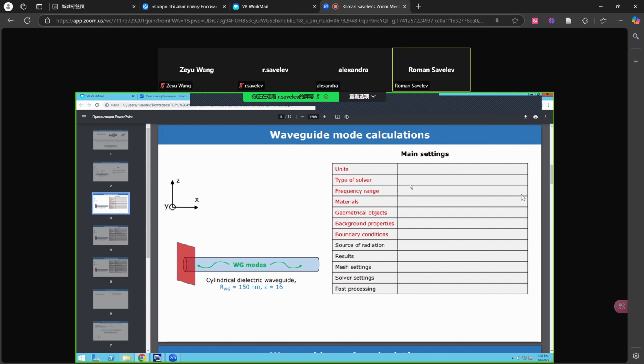So let's start making the model. Let's consider the first half of the settings that we need to set in our model. The waveguide radius is 150 nanometers. We're going to work approximately, if you take into account epsilon, with a refractive index equal to 4. So the wavelength is something close to 1 micron. For units, we can choose, as usual, nanometers and terahertz.